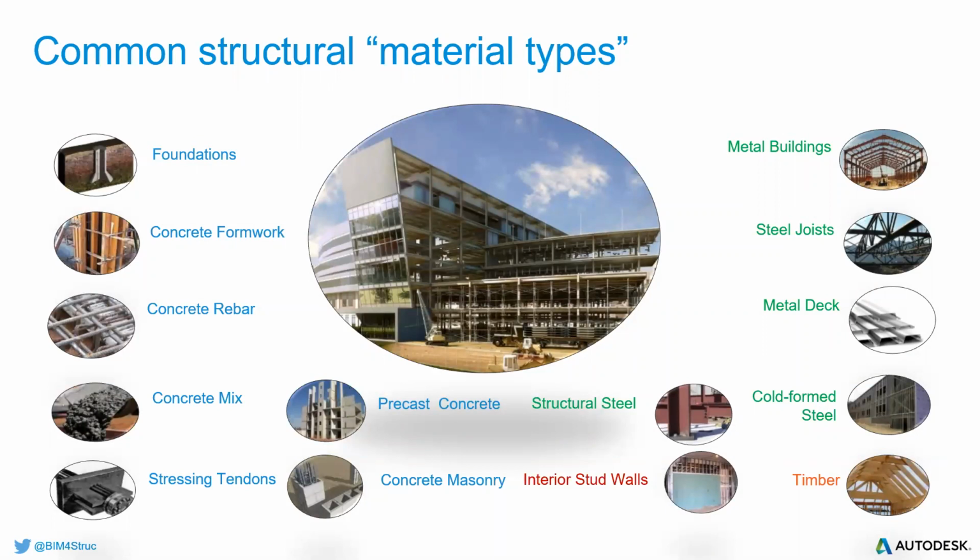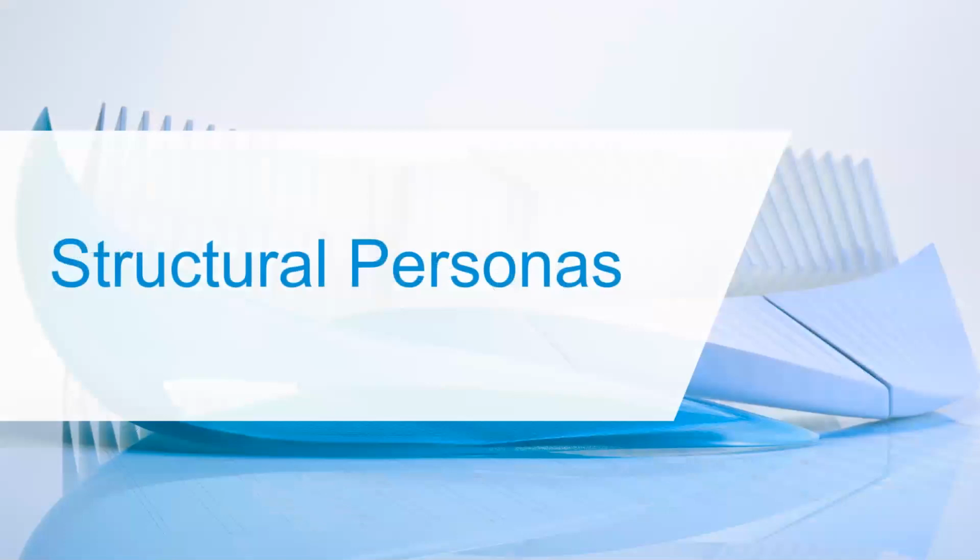So you can see, when we talk about the foundation, in many cases it is usually done using reinforced concrete, but sometimes you may also think of incorporating structural steel elements where you talk of base plates and what have you. But concrete, I think, is the most commonly used structural material for foundation. Then there is structural steel, timber, cold form steel, and metal deck, usually requiring the various plates. I'm very sure most of the structural engineers in here might have used two or three of those different structural materials that are commonly used in construction.